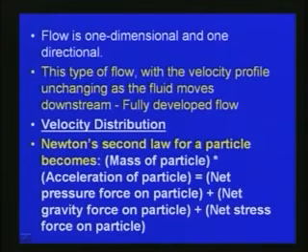So by using Newton's second law for a particle in the control volume which we are dealing with, we can write the mass of the particle multiplied by the acceleration of the particle is equal to the net pressure force on the particle plus the net gravity force on the particle plus the net stress force on the particle. So here we use Newton's second law to derive the equation.